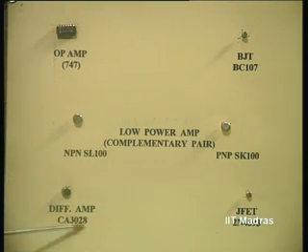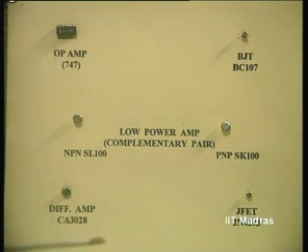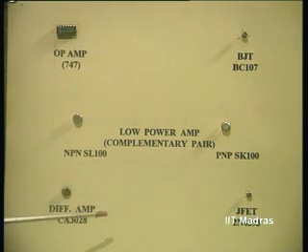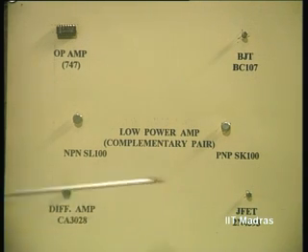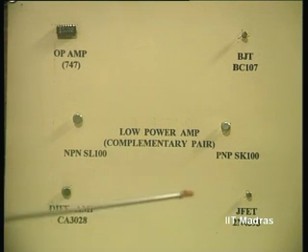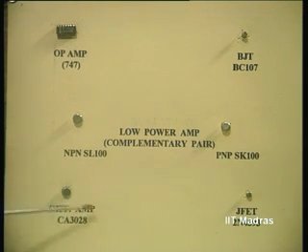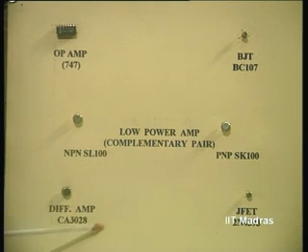Then we have another unit which we had discussed in the class, the differential amplifier. This comprises a pair of matched transistors with a current source, with all the biasing incorporated in it. Collector loads are kept open. So, the 2 collectors are open collectors, so that you can connect whatever you want. So, CA3028 is a very useful differential amplifier used for both video as well as wideband and high frequency IF RF applications. This also we will see later, how this differential amplifier can be used.